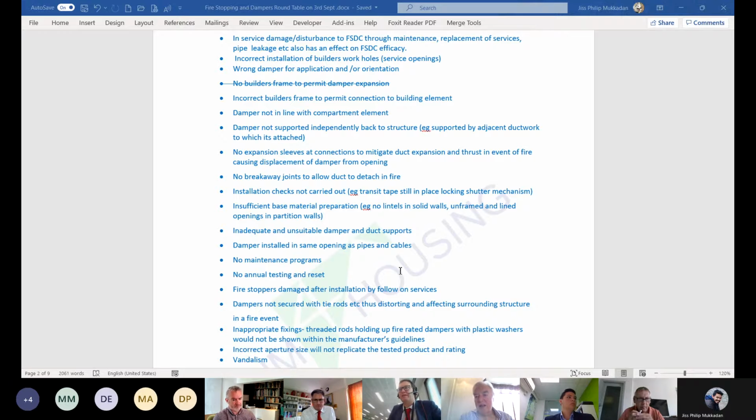Sorry, yes. It's quite hard to articulate, because I know, Paul, from other things that we do externally. I'm down a rabbit hole with wall types. The business I worked for at one point was saying that if it's CE marked, it's fine, and I was like, no, it's not fine, because just because a damper's CE marked, if it's been tested in solid, you can't put it in flexible. If it relies on a wall with a certain thickness, and it all comes down to, I think, what you're trying to achieve: if you change something out because it's broken, you can't just go and buy something different. You've got to buy something which works within the parameters of the wall type that you've got, because it's the wall that prevents the damper from failing, because it is a supporting construction. And that's the bit in my experience we get wrong in every job. We build the walls wrong.